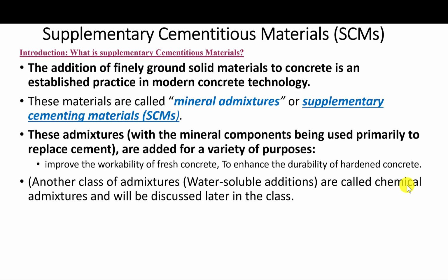We add them to improve the workability of the fresh concrete or enhance the durability of hardened concrete. There is another class of admixtures, the water-soluble additions, referred to as the chemical admixtures. Those will be discussed in the second module of the class.